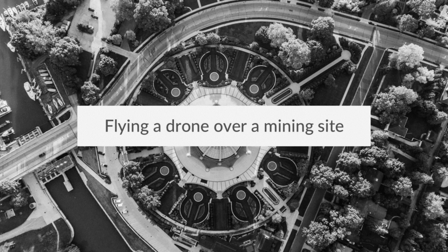Great. So since you're running DJI systems, the actual mission planning and flying of the drones is fairly straightforward, especially since it can identify, for the most part, what sensor it's actually carrying, correct? Yeah. So with the DJI specific sensors, that's pretty straightforward. With the non-DJI sensors, there's a little bit of tweaking on putting the camera parameters in, but once you put the camera parameters into the software, it works out flight lines, spacing, and the amount of overlap and flight speeds, etc.